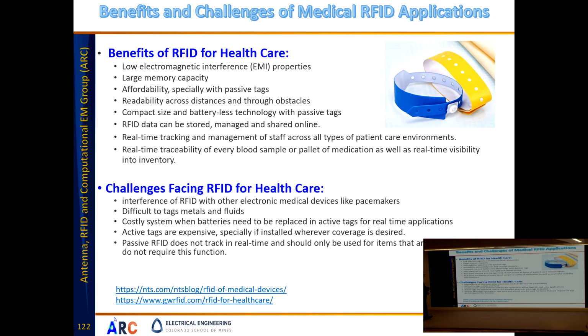If you really need real-time traceability, then you need to have active tags working all the time. Active tags use RF signal. There is so much other medical equipment that uses RF signal, so there might be some interference there. And that's something that is a little bit difficult. It has to be managed accurately, where to put active tags and where to put passive tags in the medical environment.